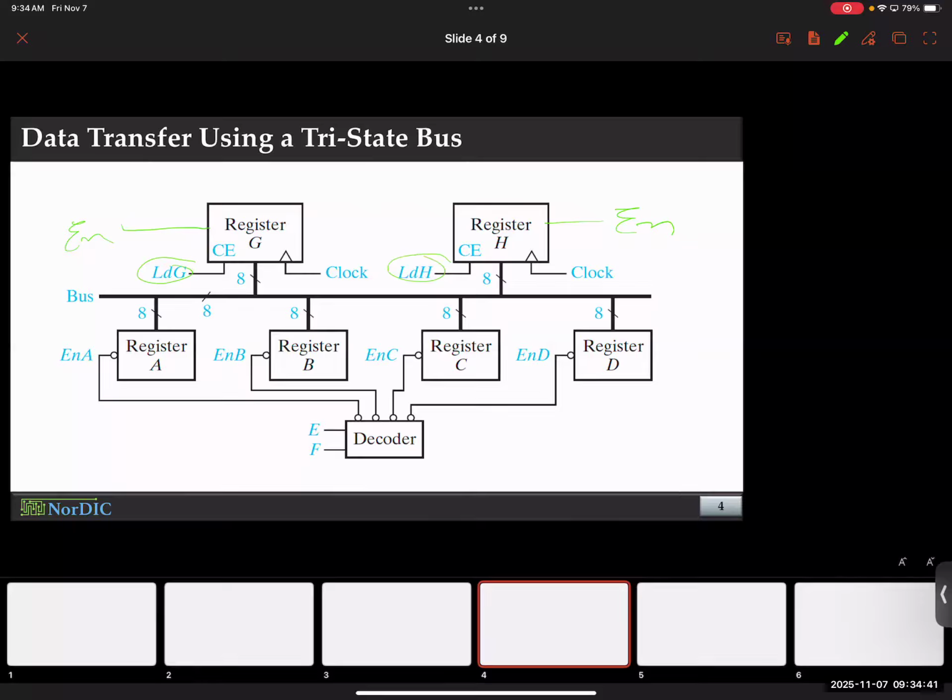You know why? Because flip-flops will always respond to clock, right? The moment there is data here, this data will be... please visualize with me. Don't give up. Let's do it together. So this is a register. Inside this register, you have flip-flops. What kind of flip-flop? For the most part, D flip-flop. Where will your inputs be connected? To the D input. Okay? When does the flip-flop send the input to the output? When the clock edge comes.